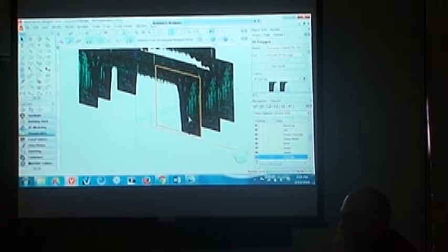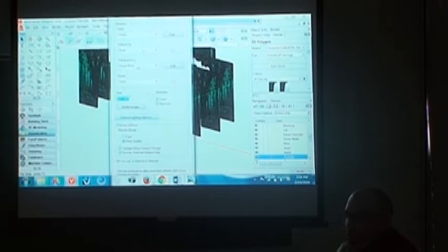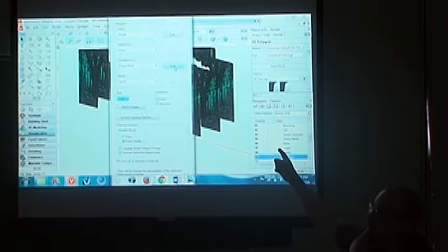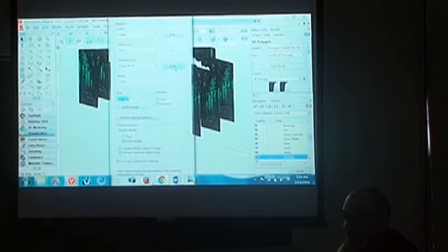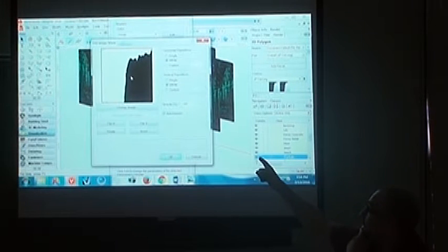When I created the object, if I go to one of these legs I already have created and look at the texture it created, you can see that under transparency it has an image mask. So I could go back into any image I've put in. If I just created an image prop without the transparency, I could always go back later and edit the texture, say use an image mask, and add the mask in later.